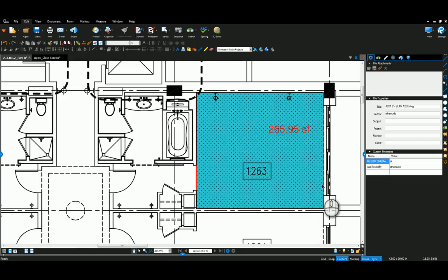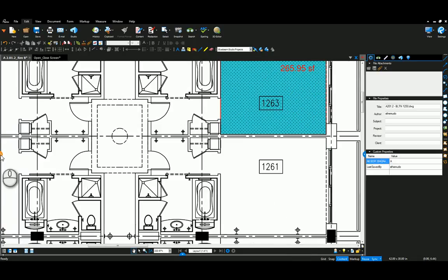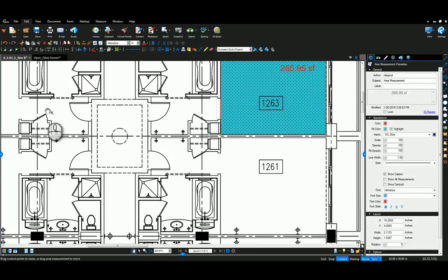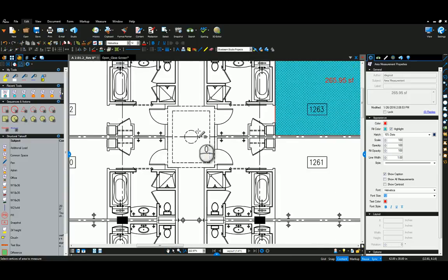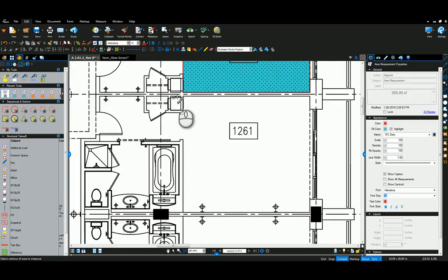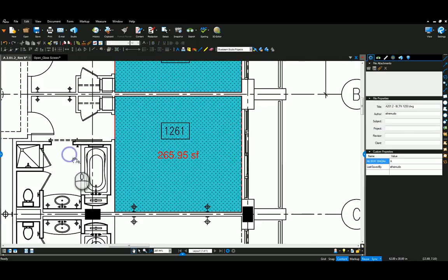Now that I've done that room, now that I've done that markup, just as any other Bluebeam application, I can come over to my recent tools and grab that from there, and right away come over without modifying it again and put in that same markup. If it's a different size room or whatever, it's taking on the properties of that same pattern that we did.